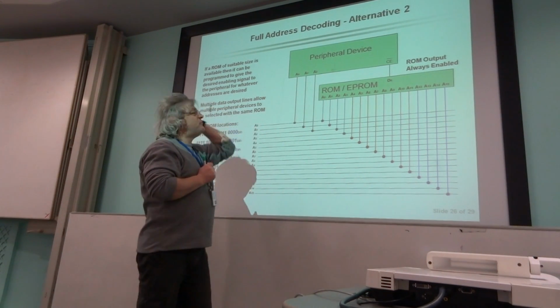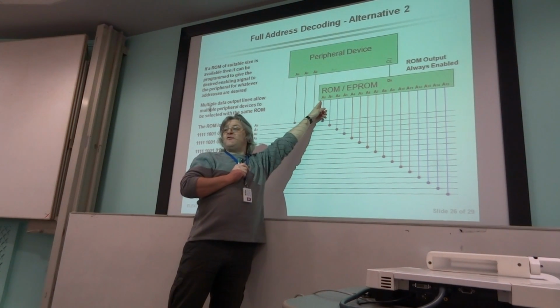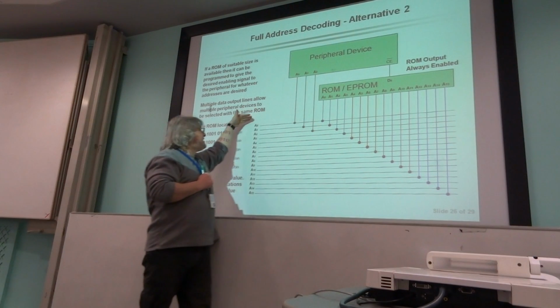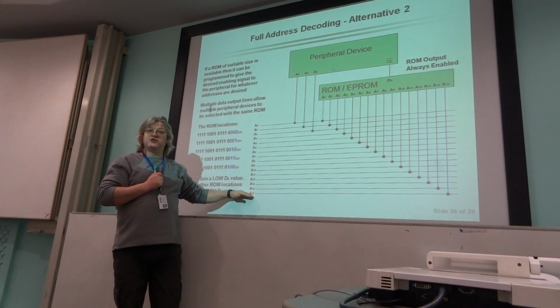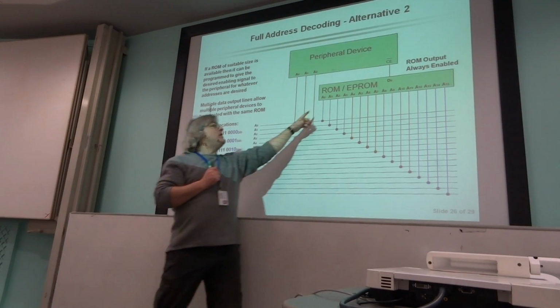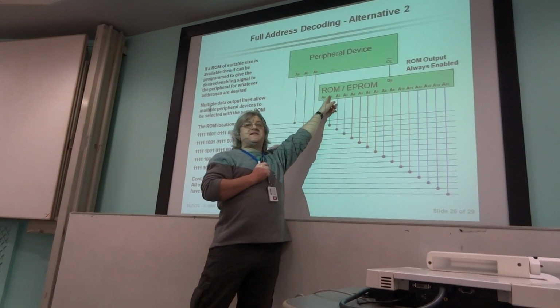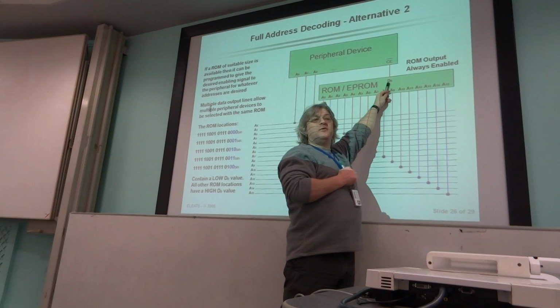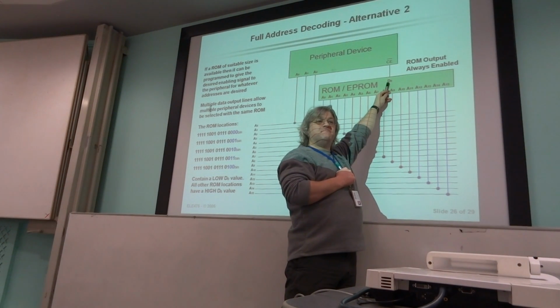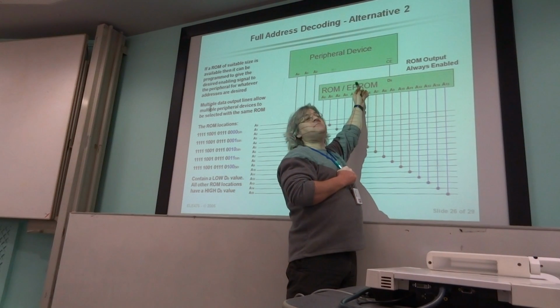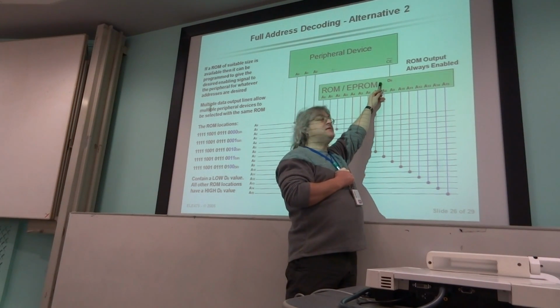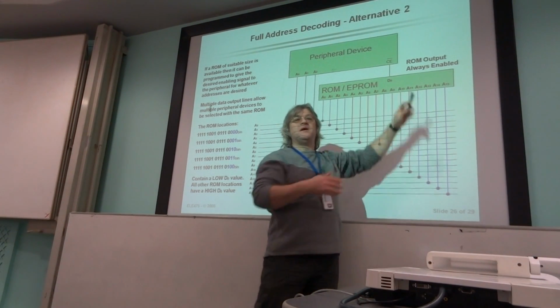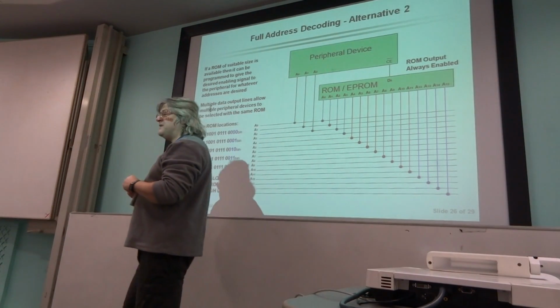And what we've done is we've written into the EEPROM, and this is a 64K EEPROM, because the address bus here has 64K different combinations, and only 5 of those 64K combinations have D0 value low. And this could be an 8-output EEPROM, so there'd be a D1, D2, and so on, but we're ignoring all of those.